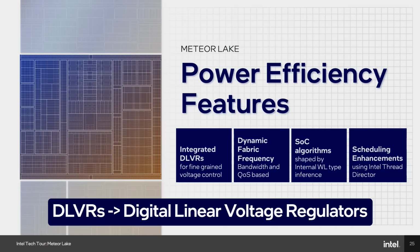So for Meteor Lake, there's a few things that we really focus on there. The first is the DLVRs. DLVRs we integrated into Meteor Lake in order for us to allow fine power control of each of the IPs. It allows us to control individual tiles, but it also allows us to go to the IP layers themselves to control the performance of that IP, and set the right optimization point based on the workload itself.